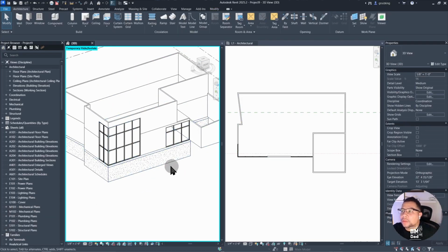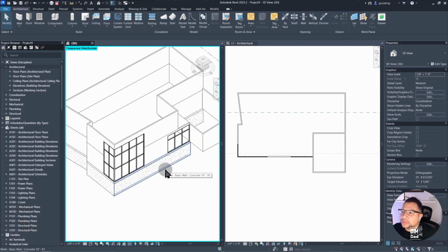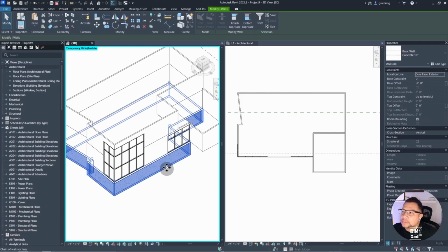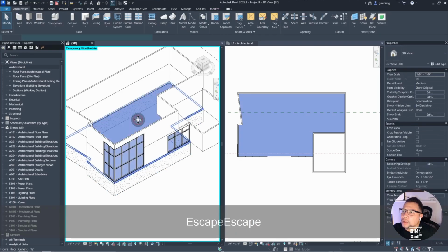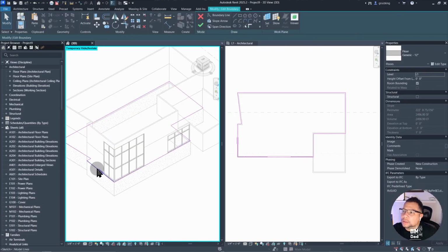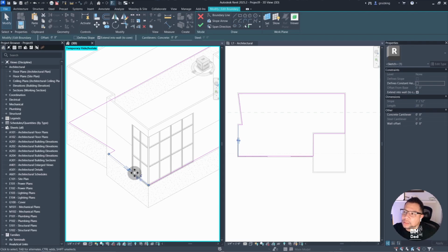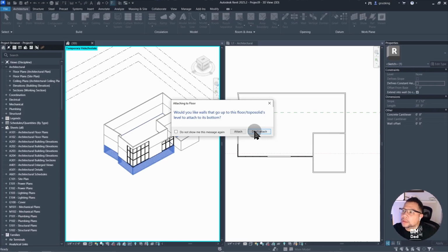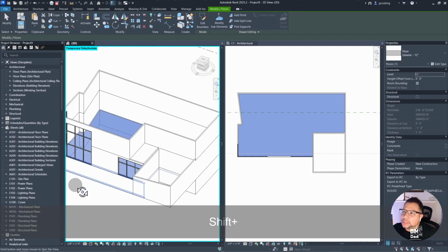Now, if that's the wrong thing and you're tasked with fixing it, you're simply going to select your foundation walls, detach, select the floor, and then go in and offset by clicking the flip symbol. You can see as soon as I selected a sketch, it showed the flip. Hit done here. And again, I'm going to say don't attach. And that's a basic overview of sketching a floor.